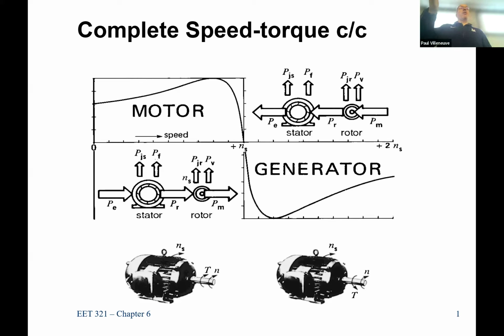So an induction machine will always operate at a lagging power factor, whether it's a generator or a motor. Which means to start an induction machine as a generator, I need to put the voltage on. It won't run otherwise, correct? Yep. You can get it spinning, but it's not going to create any output power, convert any power to electrical power, until you have a voltage on the output. I need an external voltage first. First and always, because the moment you pull the voltage away, that magnetic field is no longer available, because your voltage is what's providing the magnetic field that gets induced in the rotor. It can't provide it itself.